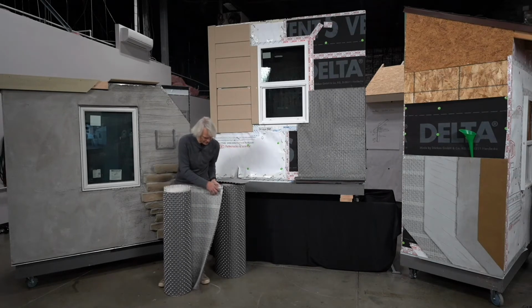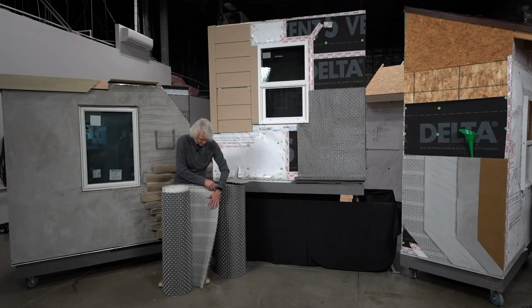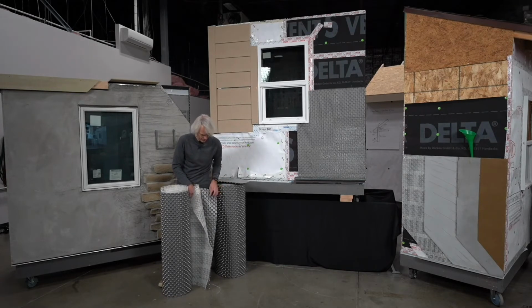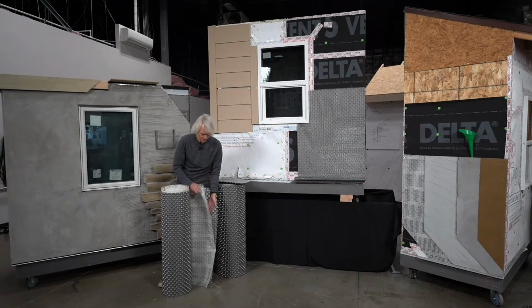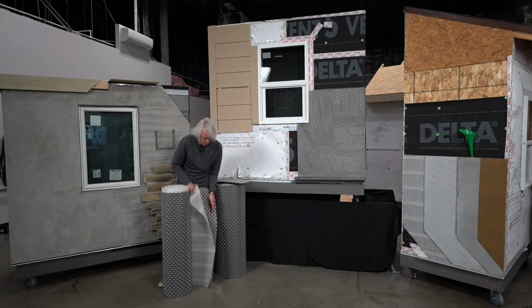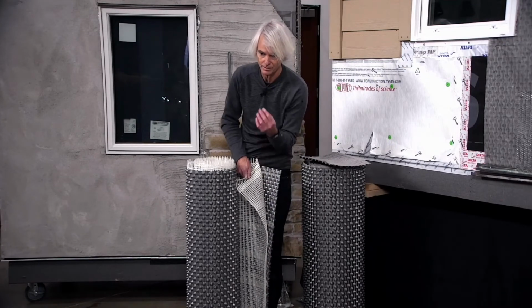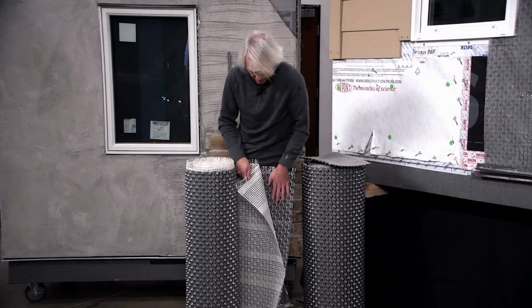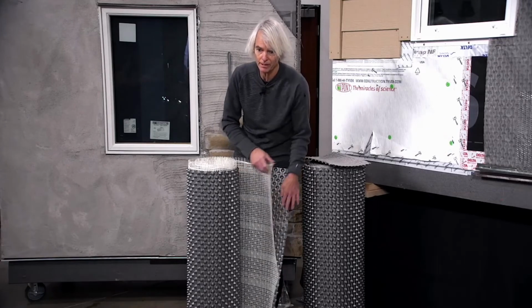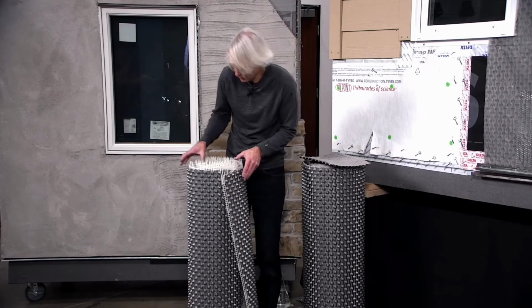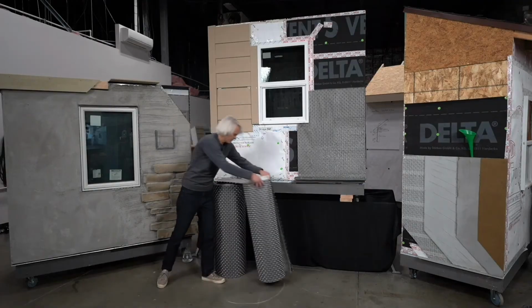And on the front side, I just wanted to point out that this is the integrated wash-treated fiberglass product, but we also have drainage channels that are molded into the front of this product. Does this allow for water to drain out of this surface and down on the front? So if I get water into the masonry material itself, does this facilitate a primary drainage plane right here, and then another rapid drainage plane on the back? We want to look at that quickly to show what would happen.